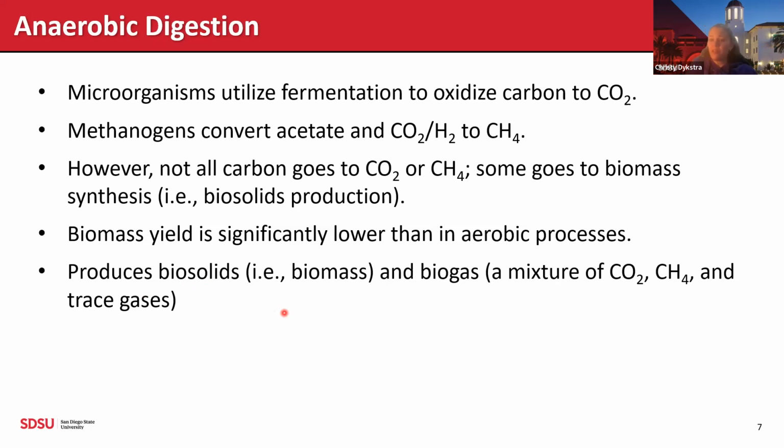But oftentimes they haven't had a lot of pathogen removal in anaerobic systems, so they typically won't apply these biosolids to crops that are going to be eaten by people. So maybe alfalfa for cows or something like that, but not really food crops without additional processing.